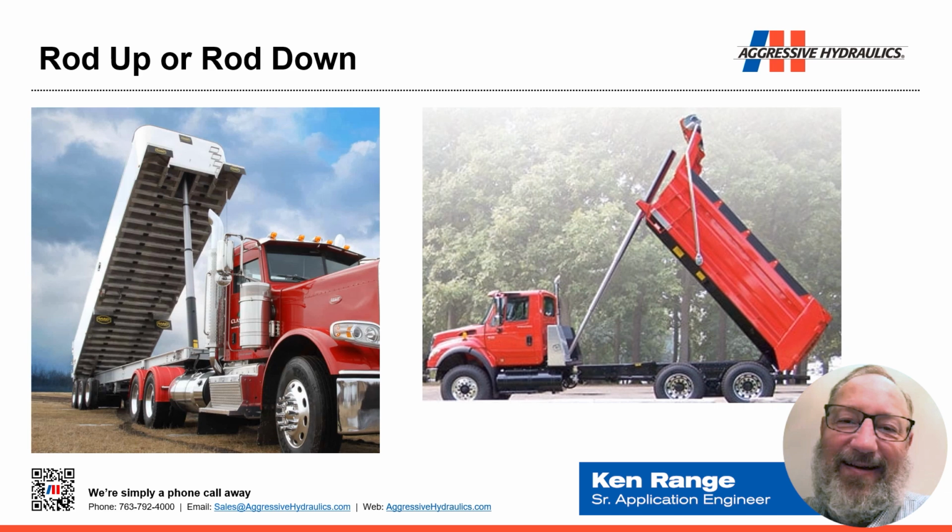In that application, they obviously have a significant amount of room to plumb to the larger case diameter that's mounted to the top of the flatbed. That's fine. It doesn't matter to the performance of the telescopic, whether it's case down, or we usually say rod up or rod down. On the right-hand view, it's likely that all the ports are located in the rod end, and that the area behind the cab within the body of the vehicle or the frame of the vehicle is so tight that they only have room for that smaller plunger diameter and the plumbing associated with it.